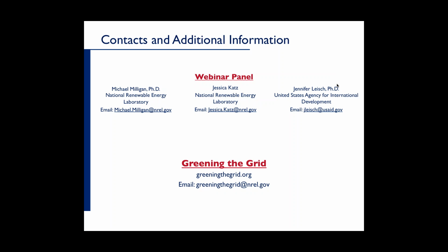That's a good question. It's kind of a hard question, because a lot of the benefits that we look at in power systems to integrate renewables come from large size, and that may not be possible in many cases. So with an island system, I think the issues are a bit more acute because you can't depend on neighboring systems. Do you need storage? I won't say that you do, but storage may become a more attractive option.